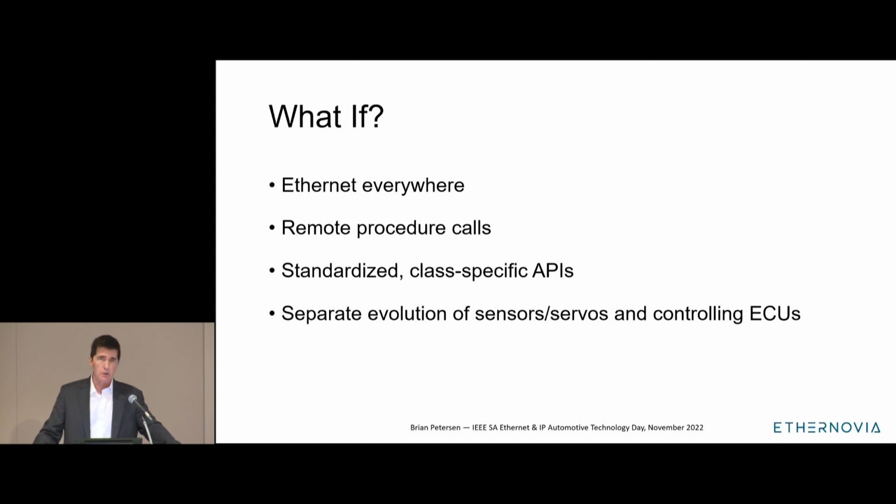Okay, if I'm understanding your question, the CAN systems today have a certain latency characteristic, and part of that may be due to their simplicity. If we move to something like what I'm suggesting, which has more layers, it would take longer to communicate. Is that your question? Or how do we address that? Well, one potential solution, and again this is my purview, I'm a chip designer, is to put those protocols in hardware. Do that work in a dedicated piece of hardware instead of a processor, and then you can eliminate the latency problem. Okay, thank you.